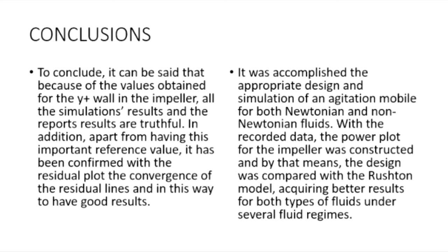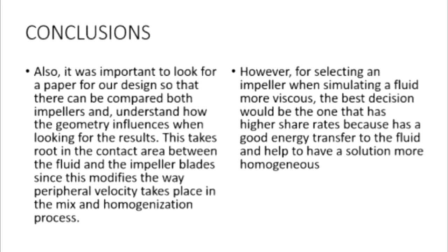Also, we appropriately did the design of the impeller, we recorded the necessary data and compared the new impeller with the Russian, where we found that the new impeller is better than the Russian for both viscous and non-viscous fluids. It can also be concluded that the new impeller was correctly compared to one found in the paper, where the power number behaved in a similar manner in both cases. And so the design is a good proposition for an impeller.